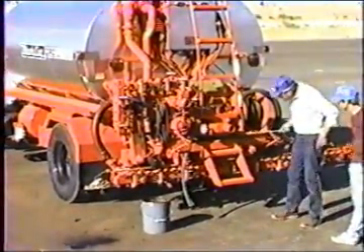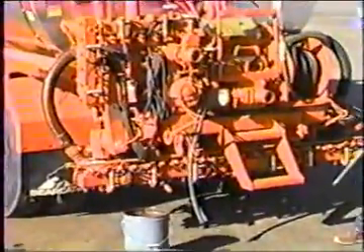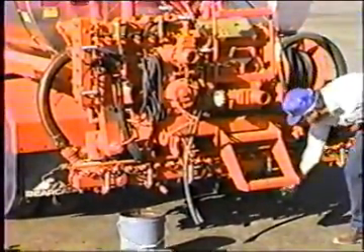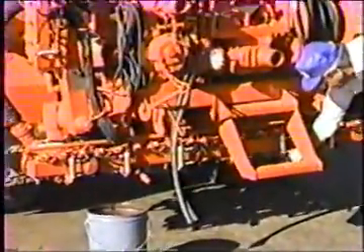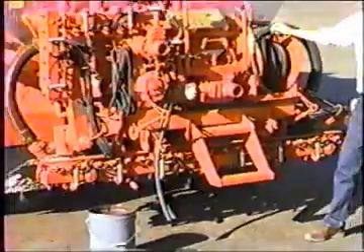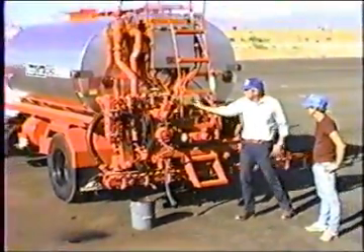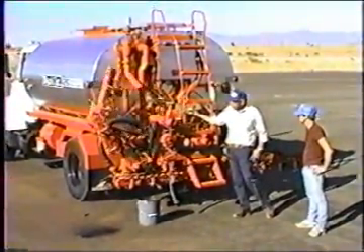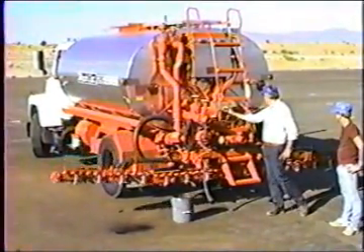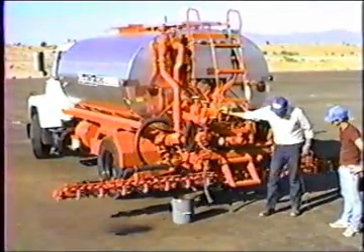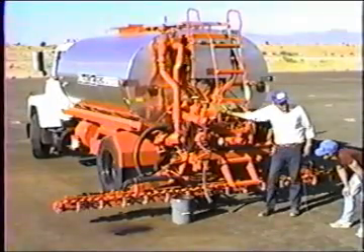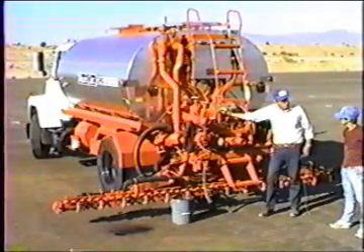Down underneath, and actually you'd have to crawl on the ground to look at it, right down underneath, dead center, back on the spray bar carriage, there's a big bolt. Right dead center is near the hydraulic cylinder that raises and lowers the spray bar. That's the down position control. That is, we want to put the bar down height-wise. We want it to go down to the same height every time without having to get out and measure it. And we can adjust that.